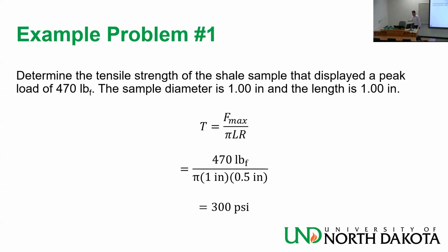This is a value typical of what you see for gypsum. If you use a gypsum sample of 1 inch diameter and 1 inch length, you would expect the failure to be around 500-pound force, between 400 and 500. Not that bad.